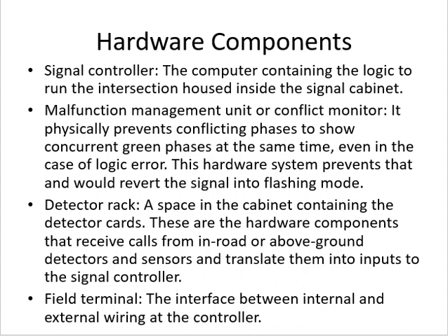So obviously we are talking about an intersection where the signal is installed. The detectors could be installed in different directions, and each detector could be connected to a different detector card. When the signal comes from that sensor to the card, it will translate it into some sort of input, like the number of vehicles or the speed of the vehicles, and then it will be sent to the signal.